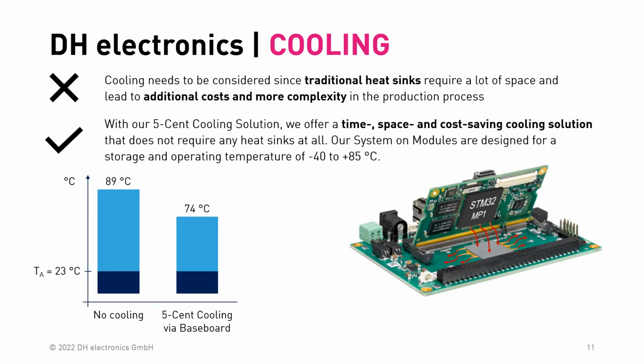We used the STM32MP1 in a closed box. As you can see on the right side, we mounted the CPU of our DHCOM STM32MP1 system on module on the bottom side of the SOM. So we had the possibility to connect the CPU with a simple gap pad to the mainboard. We can transfer the heat from the CPU via this gap pad to the mainboard. On the mainboard, we have a copper pad without solder resist. It's not an inlay, it's a standard copper pad of your top layer without solder resist.